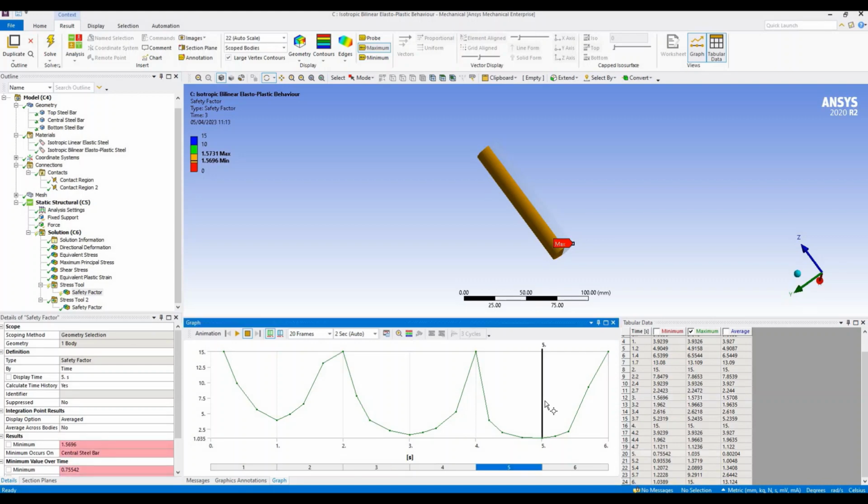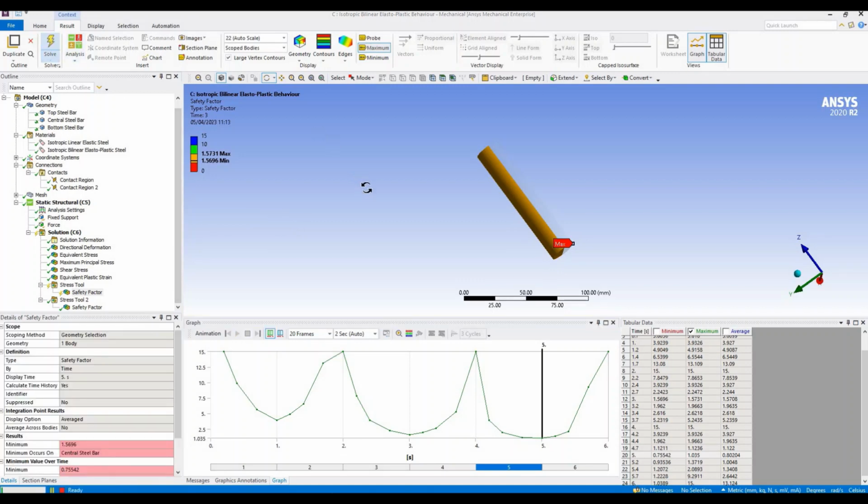And if you go to the maximum load applied to this case, which is 100,000 newtons, you will see that the safety factor is becoming dangerously close to 1 in many points, and actually in the majority of the points you are under 1, as you can see in these results here. So for 100,000 newtons you are definitely in bad conditions.